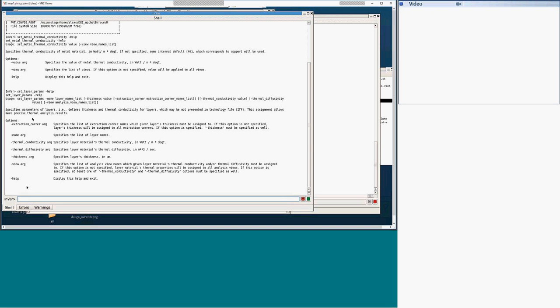And this command you set thermal conductivity, thermal diffusivity, and can define thickness. For layers that are above substrate, you usually do not need to do this because thickness is part of the ITF or IRCX file that you read in. But there are also substrate layers like diffusion layers, thermal isolation trenches filled with different material. So for these layers, you define thickness because this is not part of ITF. There are no diffusion layers in ITF and RCX.